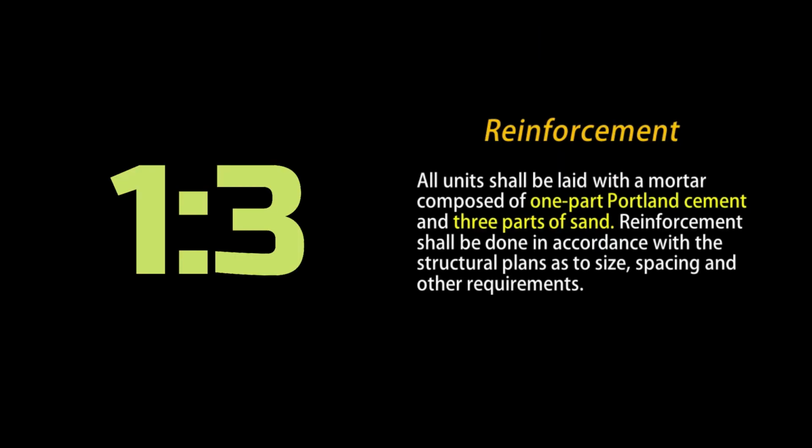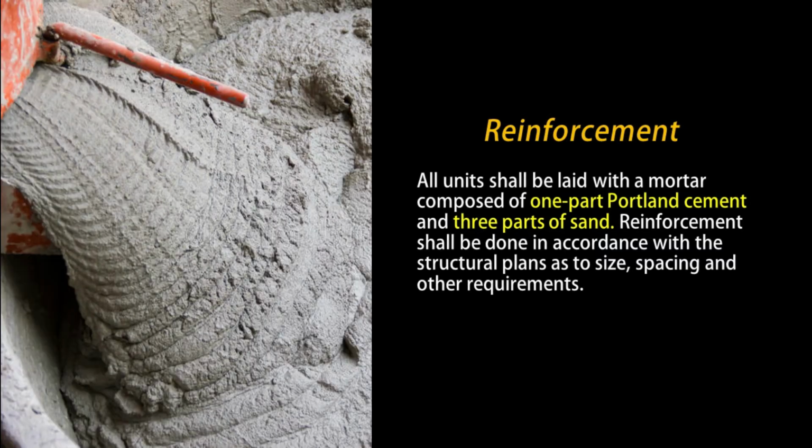Reinforcement. All units shall be laid with a mortar composed of 1 part Portland cement and 3 parts of sand. Reinforcement shall be done in accordance with the structural plans as to size, spacing, and other requirements.